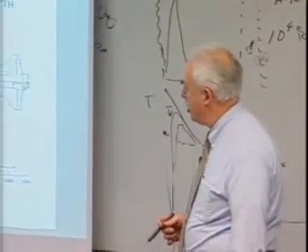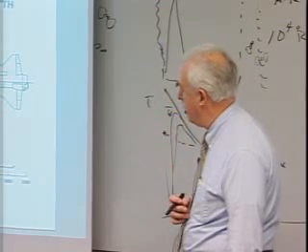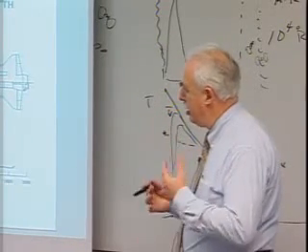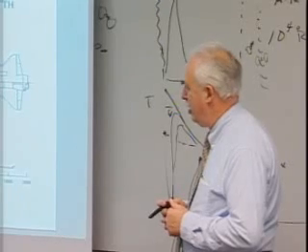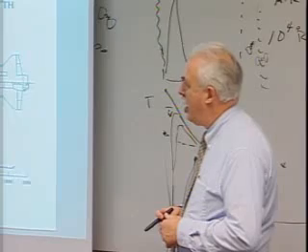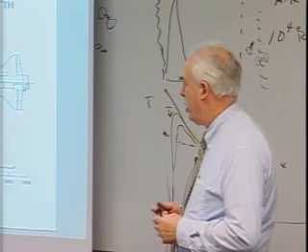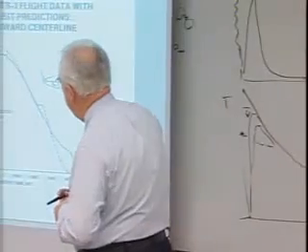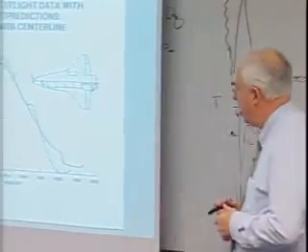We did consider the surface catalysis, which I'll show here after a while, but we did not really include the non-equilibrium flow in the inviscid flow, what I've been talking about here with Apollo. That was beyond our capability, to do finite rate chemistry in the inviscid flow field. Okay, why don't we go to mid-body now?